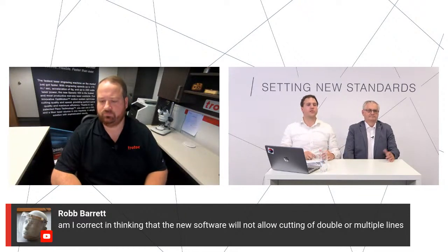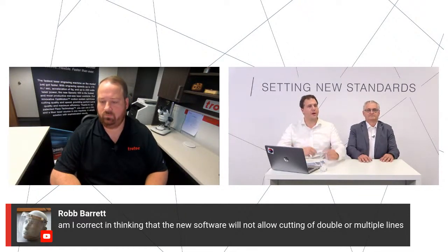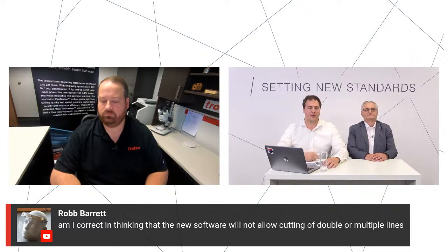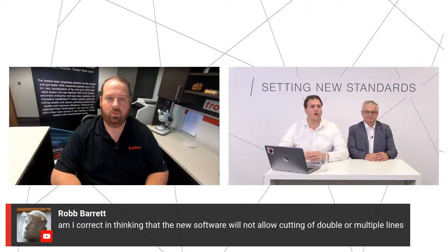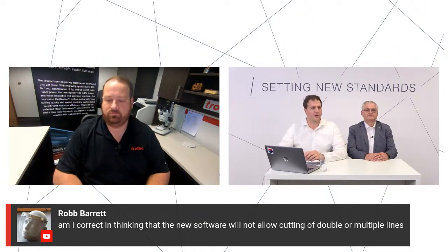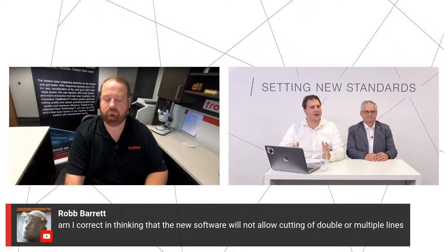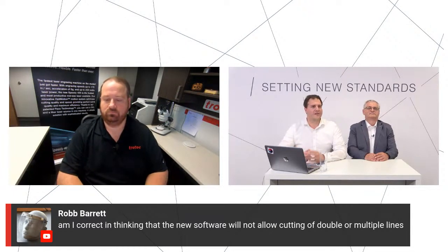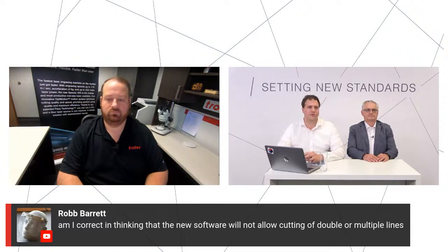Yeah, of course, it's still possible. Per default, skipping overlapping cut lines is actually off. Some might know this feature, especially in the printing industry. It's commonly called common line cutting. So per default, it's off. If you do not activate it, double lines would be cut twice. But if you activate it, you can move your design files as close as possible together and save a lot of material, but not just material, also reduce your processing time a lot because you're not doing it twice, just once.